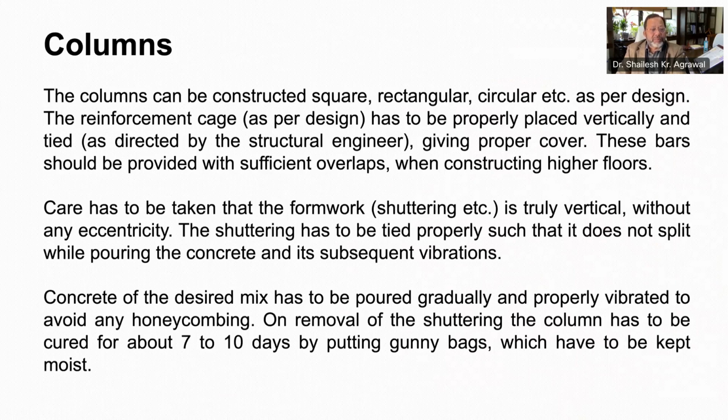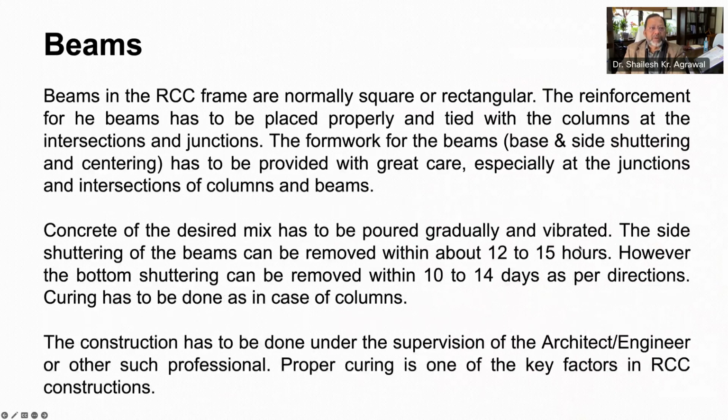and subsequent vibrations. The concrete of desired mix shall have to be poured gradually and properly vibrated to avoid honeycombing. On removal of shuttering, the column has to be cured for 7 to 10 days by putting gunny bags, which are to be kept moist. Now let's move to beams.